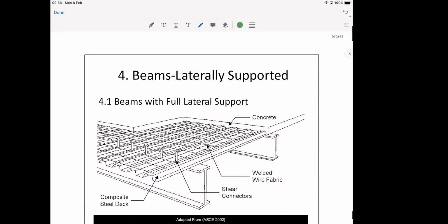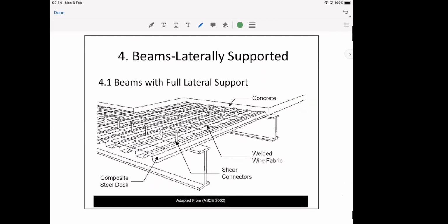All right. Now, in a nutshell, we use the shear connectors to connect the metal deck to the beams, and this will help brace the beam automatically. This system is very popular abroad, especially in the US and in Europe, because it's very quick. Actually, you can do it as a one-man job, with a man and a machine connecting these shear connectors to the metal deck and the beam. One floor can be done in a few hours. So it's a very, very quick process, and people love that.